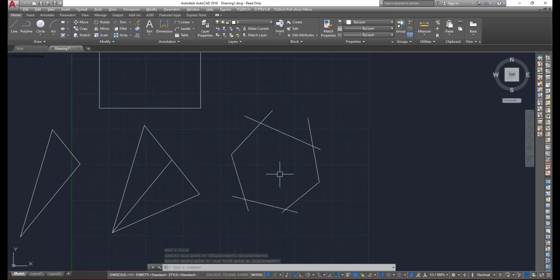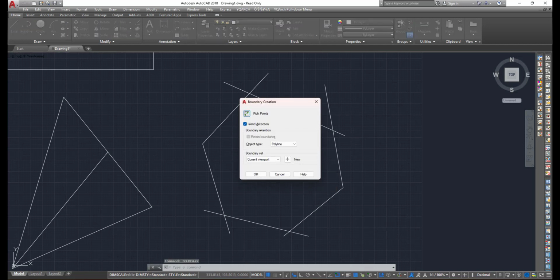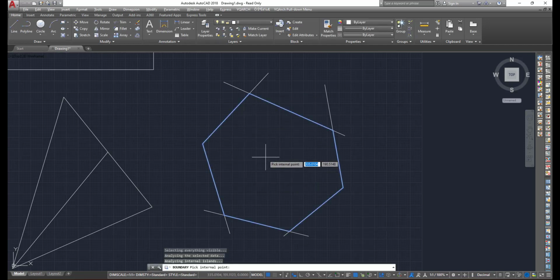Also, for example, if our intention is to calculate this area, for that I use the area command. To get the area command, you have to type AA, enter. So I have to click the particular area which we want to calculate, by clicking the first point, second point and third point. Rather than doing this, I don't want to calculate the whole object. I want to calculate only this much of the highlighted area. Before calculating the area, make that portion a boundary by using BOU, then pick it, click that particular area and enter. So it becomes one closed boundary now.